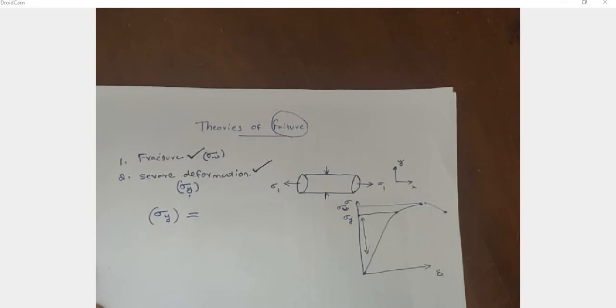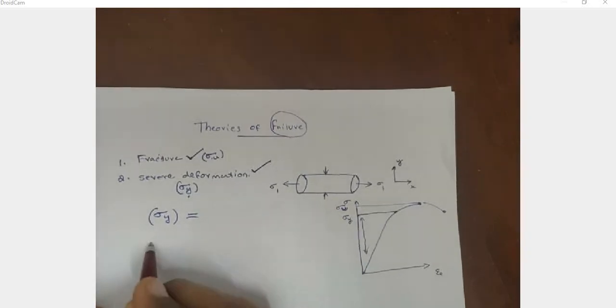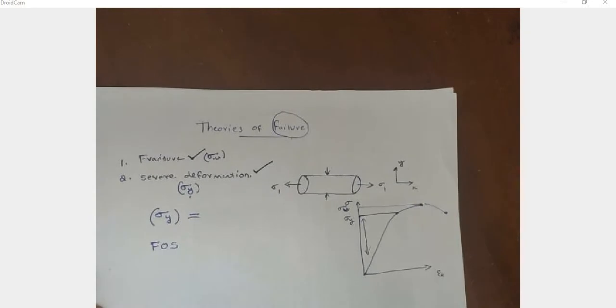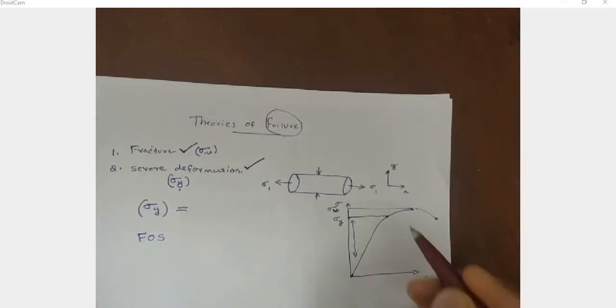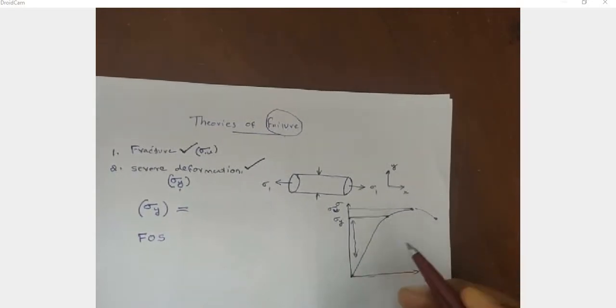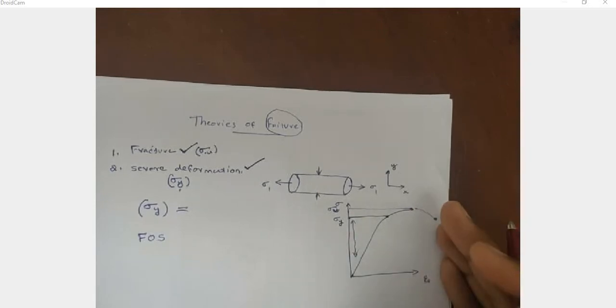And next, something we studied earlier is factor of safety, FOS. What is factor of safety? If we design based on sigma y, then with any change in the stress applied on the member, there is a chance of crossing sigma y. Different uncertainties may develop on the structural member, like an earthquake or severe wind.